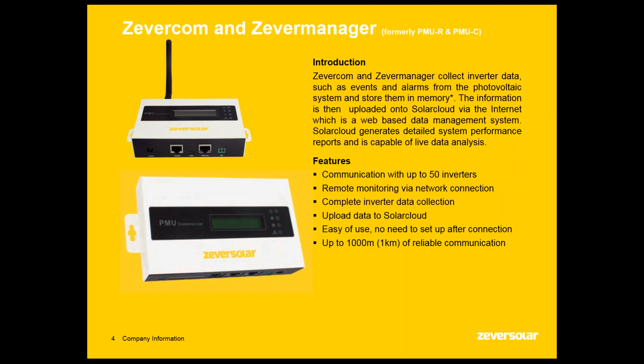Both ZeverCom and ZeverManager are IP20 rated, unlike the inverter which is IP65. Therefore, they are not suitable for external mounting without the use of an additional weatherproof enclosure. These can be picked up from your local electrical wholesaler for around $15.